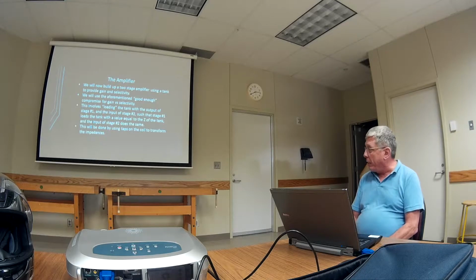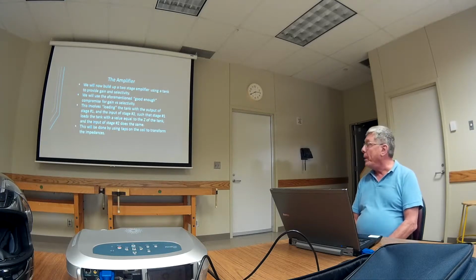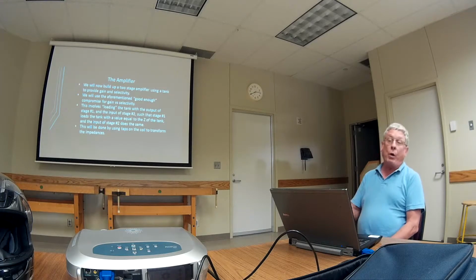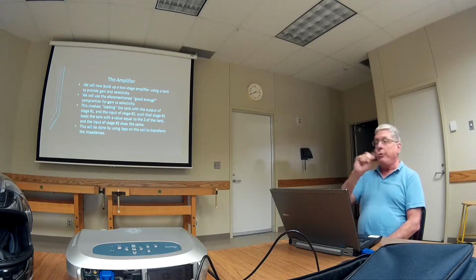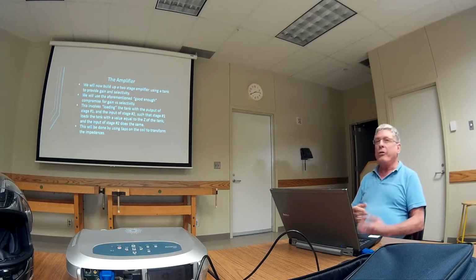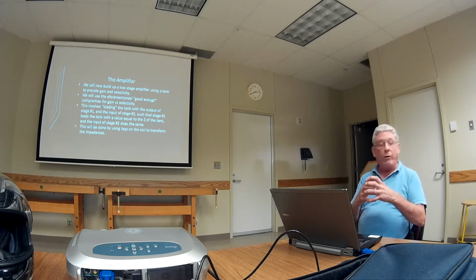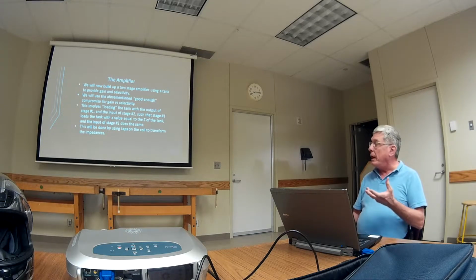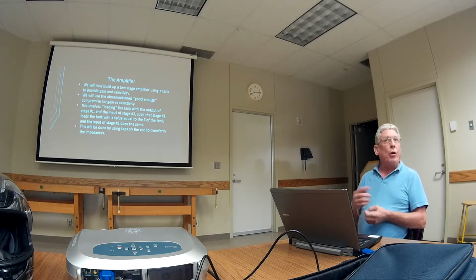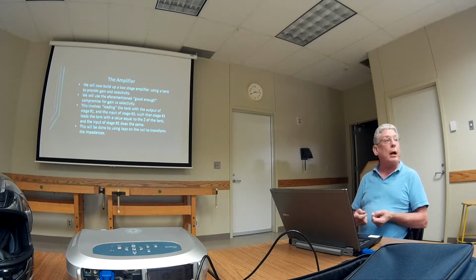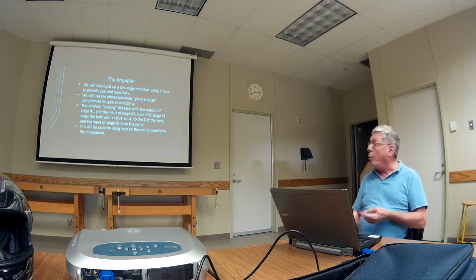We're going to do that using taps on the coil. Now, instead of taps, you can also use links. Like if you want to tap at 2 turns, you could use a 2-turn link. What I don't like about links is that the core starts to get full of wire and you can't tell which lead is what. The other thing is, even with toroids, at least I found a lot of times, you don't get the same amount of coupling with a link that you will with a tap.